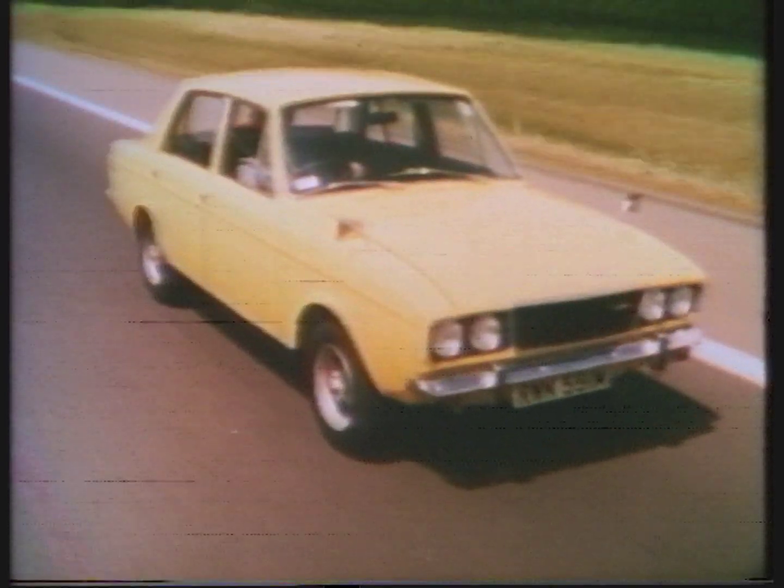The situation is, the remaining minimal unbalance is being magnified by wear or very minor fault conditions. So you've got to get what some might call downright finicky about the checks that follow. In the first condition, vibration of the front of the car at all speeds above 10 miles per hour, probably with movement of the steering wheel.